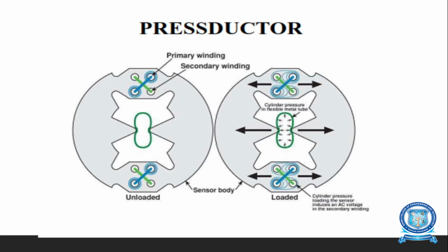And the next one is press detector. It is called radial load cells. It is basically a magnetoelastic type force transducer. In this type of transducer, the permeability of a magnetic material is altered by the mechanical stress which is developed. The main application of this press detector is ideal for applications on a wide range of processing machinery in the steel rolling mills, plastic sheet rolling industry, printing, textiles and other industry. It is also used in platform weighing, mobile scales and batch weighing systems, etc.